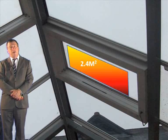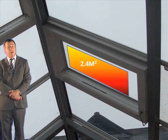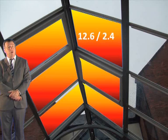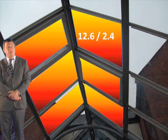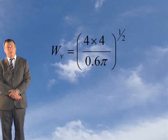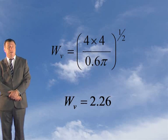The geometric area equates to an aerodynamic free area of 2.4 square meters for each ventilator, and we shall need 12.6 divided by 2.4, which equals 6 when rounded up, of these ventilators to ensure that we have sufficient aggregate ventilation area in the reservoir. The geometric area of 4 square meters is the one that we have to convert to give us a value of WV to put into the formula for M crit. WV is calculated as shown here. In our example, WV comes out at 2.26 meters. So this is a figure we have to put into the formula for M crit.